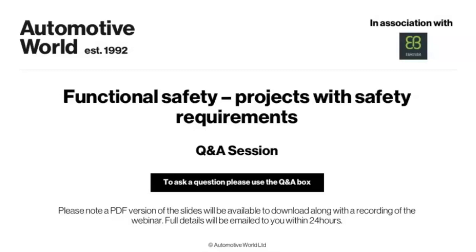Thank you. How would you provide safety to QM modules and safety modules, both of which are in a cascade? So a QM module should actually have no safety functionality. That's per definition, right? You cannot upgrade QM to safety.